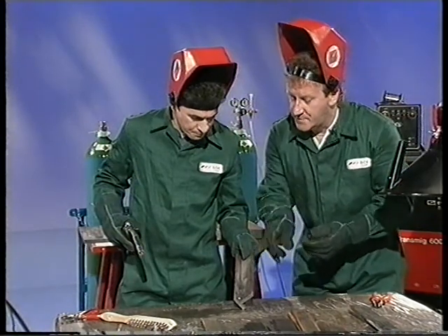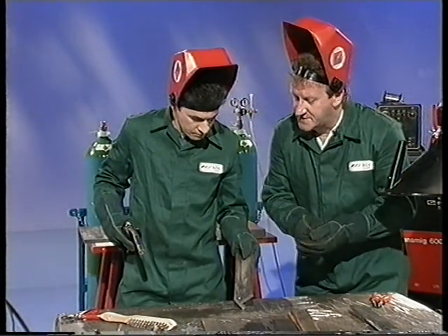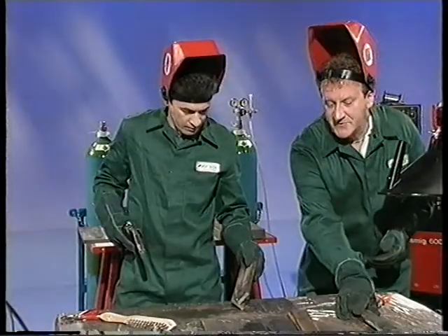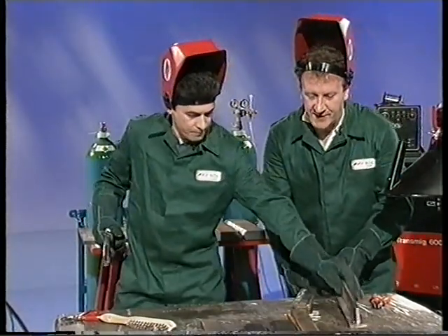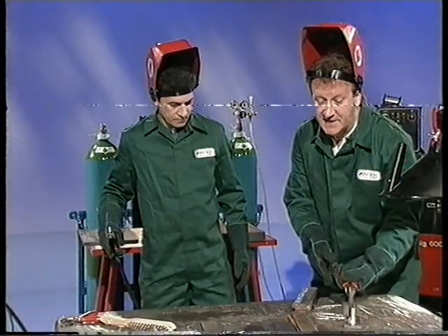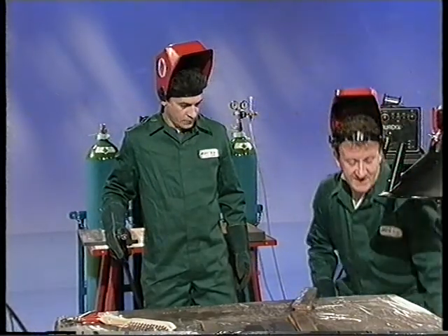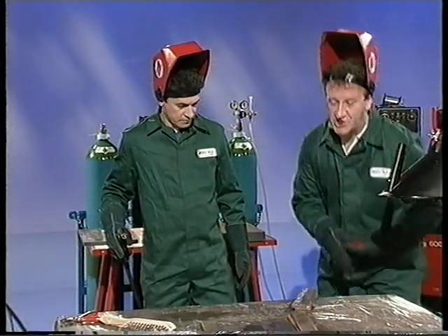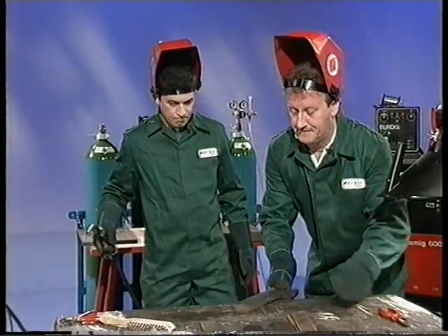The reason why I'm trying to show it on the mill scale as well is that in reality, in practice, if you've got large jobs to do, it's unlikely that you grind all of the weld joints up. Sure. But the better results are going to be attained on ground plate. I'll just pop that into the bucket of water. This is for safety reasons to quench this hot material off. It's not advisable to quench welds as soon as they're done.